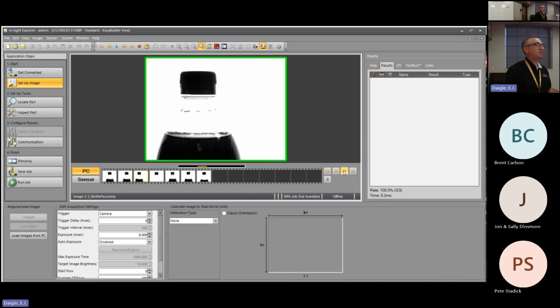When people first started working in machine vision, they tried to aim the camera at the same location every time, and they tried to trigger the camera at the exact same spot. And what they discovered was parts don't always line up in the same spot. You know, when those parts are coming down the conveyor belt and the robot's picking them up, sometimes the parts are turned 45 degrees. And I'm putting them in a case and I want to stack them neatly. So that's all stuff that's important.